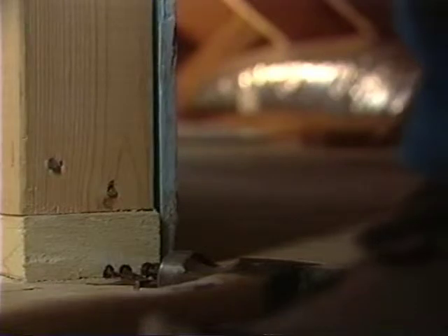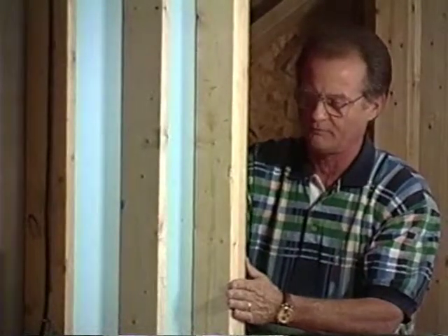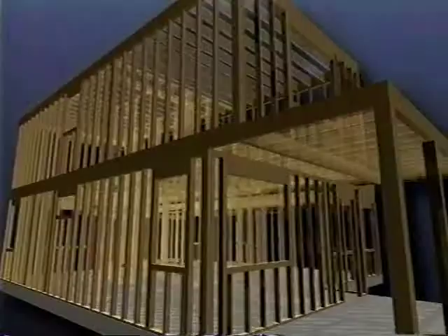Now we can see that by putting the insulated sheathing on the back side, we've created a closed cavity which will reduce infiltration, give our insulation a backing when it's placed in the wall, and also reduce the amount of moisture that can migrate into this wall. We're now ready to install insulation in each cavity.